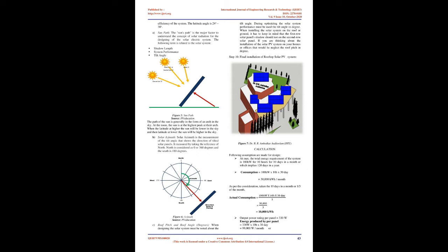Step 8. Solar panel design. Just draw a basic rectangle. You need to give depth to the module using the push/pull tool. Now select the module and make it a group. Use the rotate tool to give an angle to the module according to the location. On the other hand, we can take the solar panel from the 3D warehouse browser.